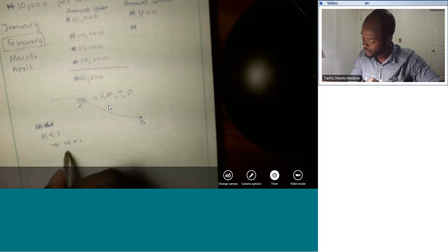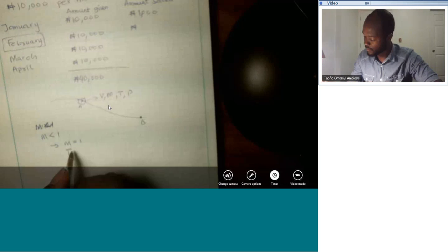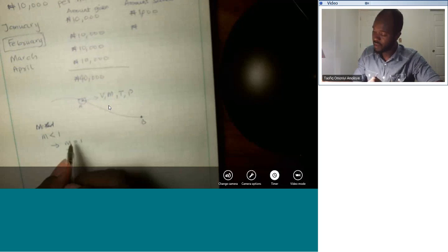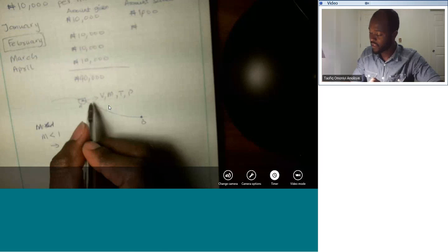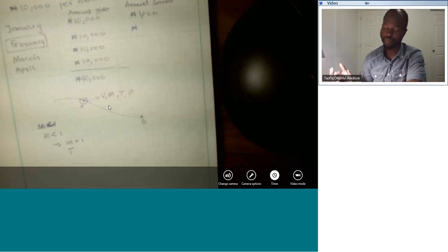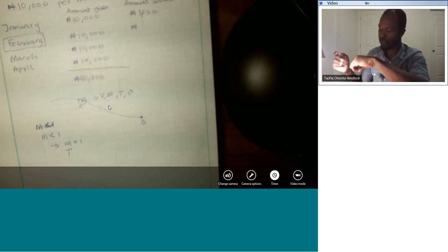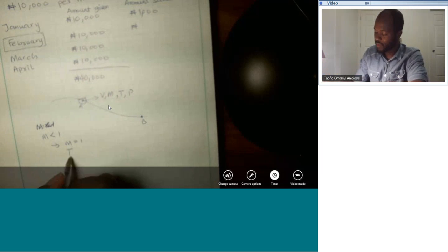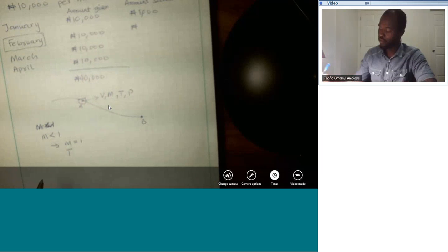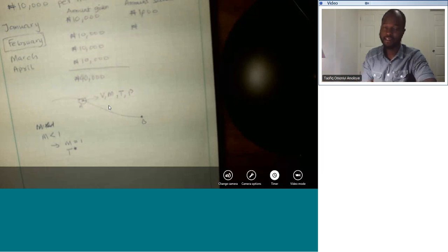Obviously, the temperature will have changed when you are speeding it up. We can also try, if it's traveling at a speed where the Mach number is greater than 1, to imagine a process whereby we are slowing it down. Just in our imagination, we are slowing it down until its Mach number is now 1. So at that point in time, which is just an imaginary point in time, we can now define the temperature at that point as T star.